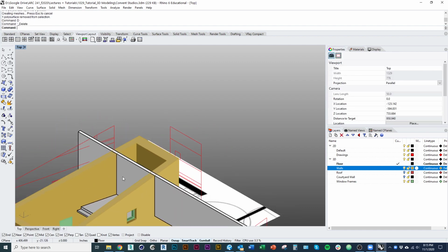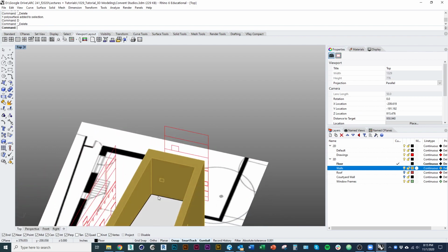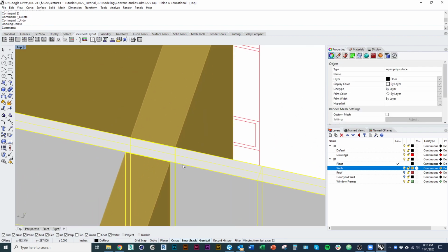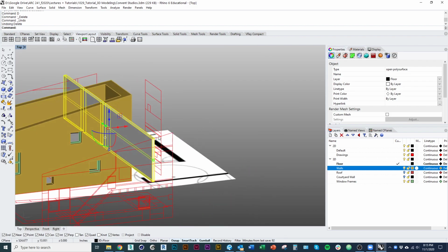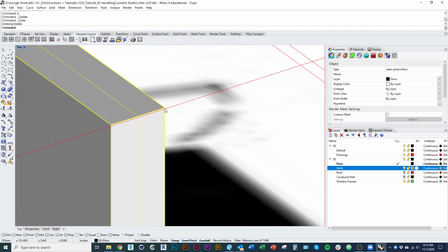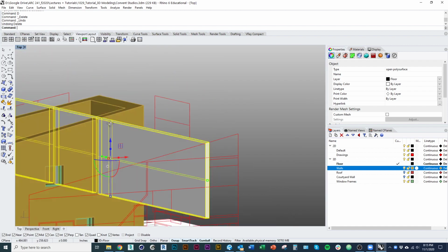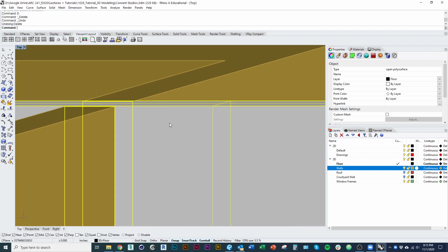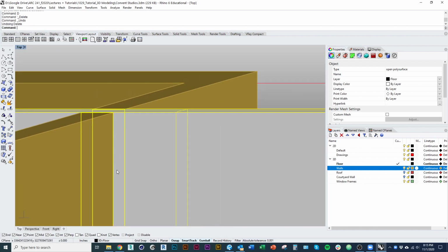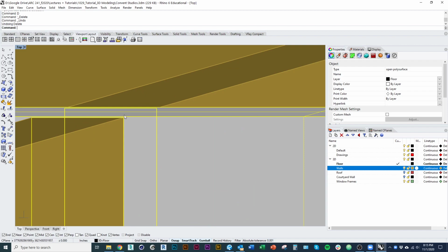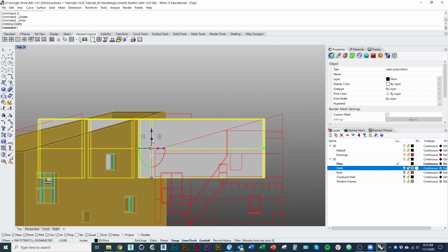Delete everything I don't. So what's actually happening here is my interior wall that I'm trying to trim with my exterior wall is above where my exterior wall is. So it's trimming with just a little bit connected at the top. So that's still one object.